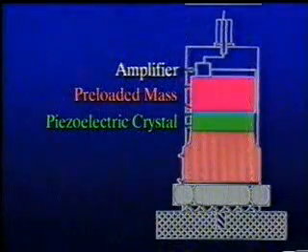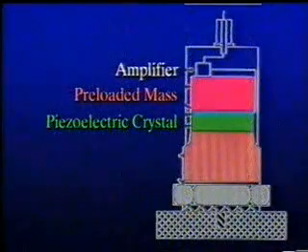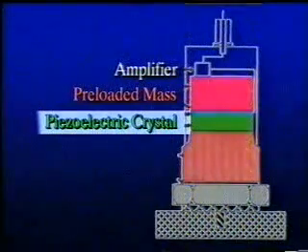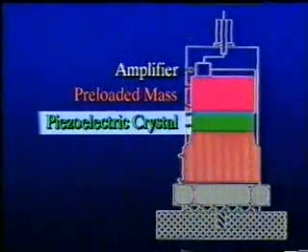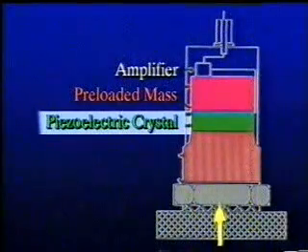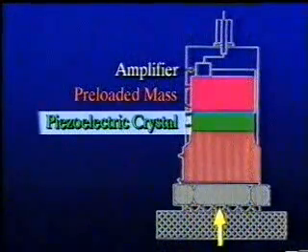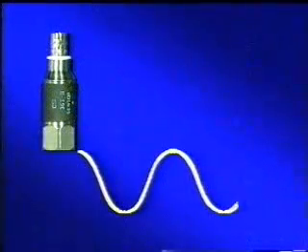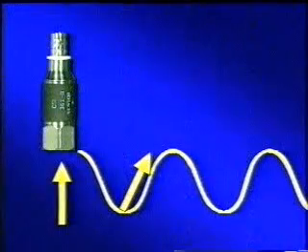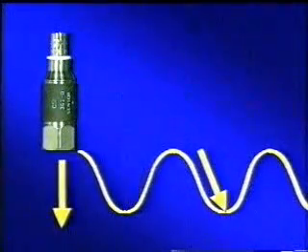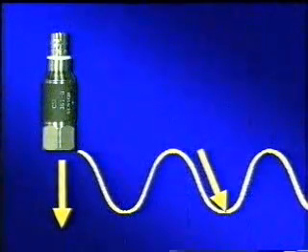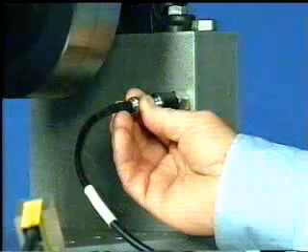Most of today's sensors, both accelerometers and velocity sensors, use pressure-sensitive crystals as the internal sensors. When the crystal is squeezed due to the impact of the vibration, a signal is generated and sent to the analyzer as waveform data. For most sensors, the impact of the vibration toward the sensors is the positive side of the waveform. Movement away from the sensor is the negative side of the waveform, or 180 degrees away.